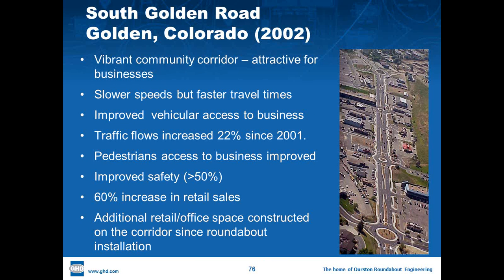What the roundabout does is smooth the speed profile. So when you see another downstream roundabout coming up ahead, you're not inclined to accelerate as though there's an amber and you have to get through it. You know that the roundabout has a very minimal queue. You're going to get through it. It's just a matter of a few seconds. So we tend to find the speed profile of corridors of roundabouts to be smoother and more uniform. To me, that translates into improved safety for access and development, because a uniform operating condition is a more predictable operating condition, and that tends to be a safer condition.